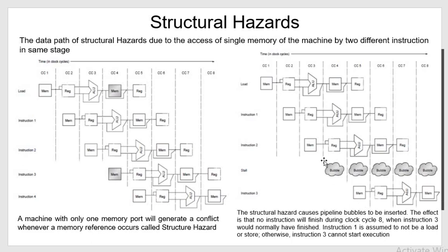So this delay of 1 clock cycle will be introduced within the one program. And again we have already discussed that otherwise we were expecting the output of instruction 3 at clock cycle number 8, but due to this bubble, due to this stall, as the opcode was fetched with a 1 clock cycle delay, the output will also be available with 1 cycle delay, that is in the 9th clock cycle.